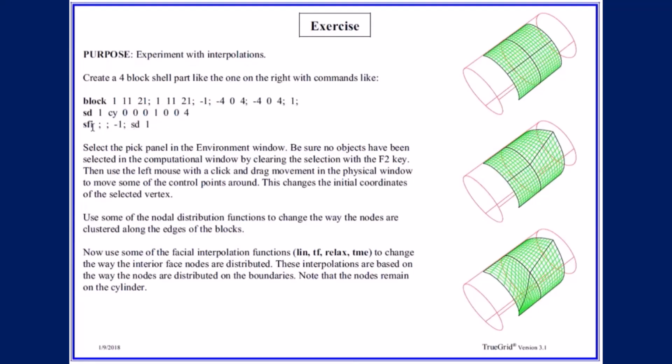And then the third command is the projection command. This is again the index progression version of it because it has an I as the last letter in the name of the command. And it's going to be the entire K face. So everything is going to get projected to our cylinder, surface 1. And that's what's spelled out right here, project to surface 1.